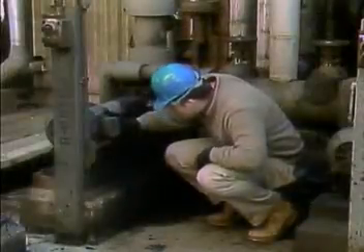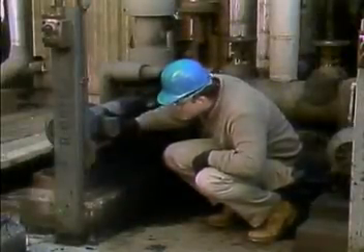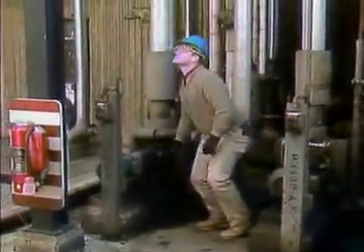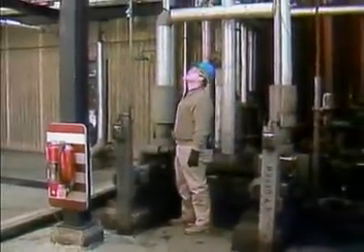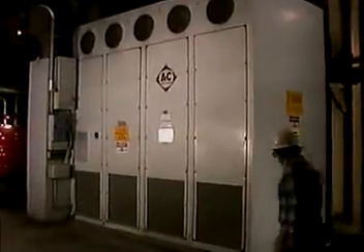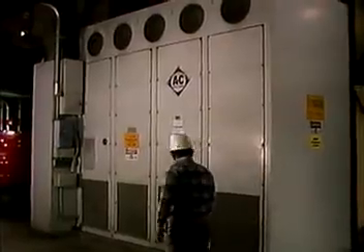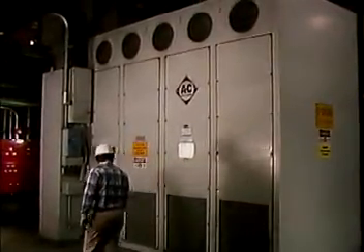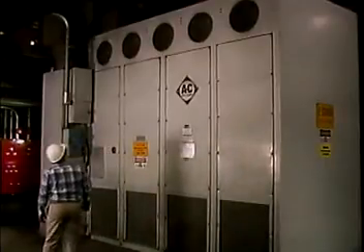You can get shocked, for example, if you're trying to identify the source of a leak and you accidentally touch energized equipment. In addition, some liquids can start a fire when they get on energized equipment. Be careful anytime you have to check electrical equipment closely. In some cases, you may smell insulation burning or see arcing, which tells you that current is going where it's not supposed to.